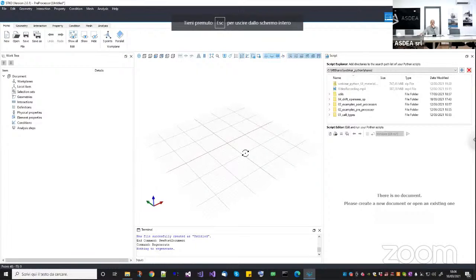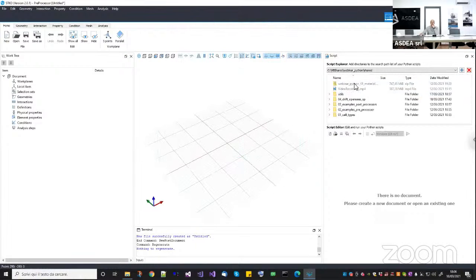Okay, so I will very briefly introduce you to the new Python API that we have in STKO version 2. For more details, you can refer to the video that we already shared on our website, because it is going to give more details. And in particular, in this webinar, I will talk about how to use the Python API for customizing the post-processing in STKO and compute the drifts from the MPCO recorder, because as you will see, the drift recorder will not work with the parallel version of OpenSees, in particular with OpenSees SP.